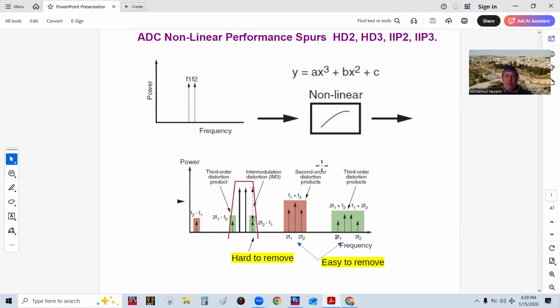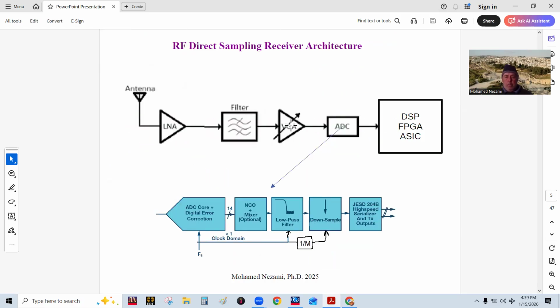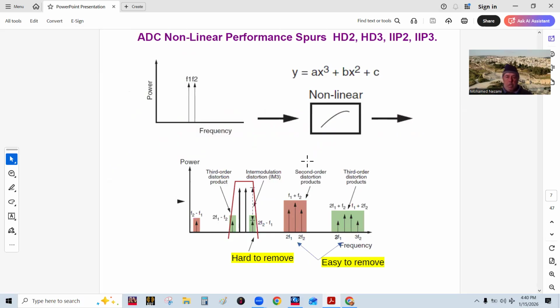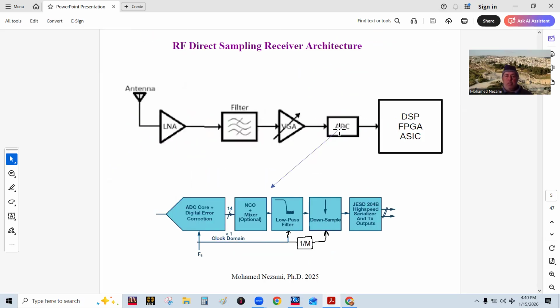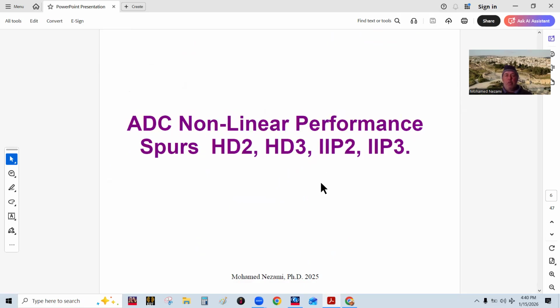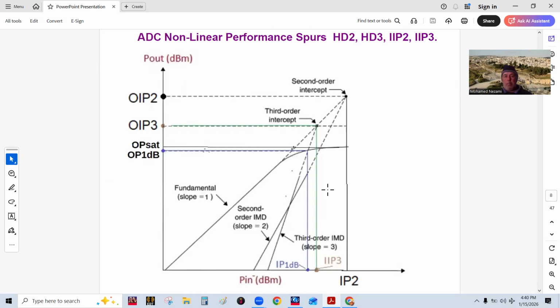Saturation comes basically from these devices and from the ADC itself, because the ADC, remember, you have the full scale, and that's the all ones, and that's going to saturate, okay? And of course, in the ADC in here, you do have differential drivers into the ADC. Those are treated as nonlinear devices, just like the amplifiers, the RF amplifiers, and the front end. Those can cause that to happen as well.